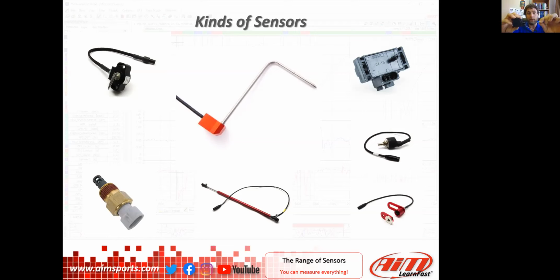We'll talk about some different ways these get used and all the different applications for them. And when you get really creative, it's a great sensor. Sometimes this is more of a go-kart sensor, but a push position sensor, usually they're about 150 millimeter stroke. A great sensor to use on a pedal. You can see this one, somebody made up their own with a little mount here that you can do different things with.